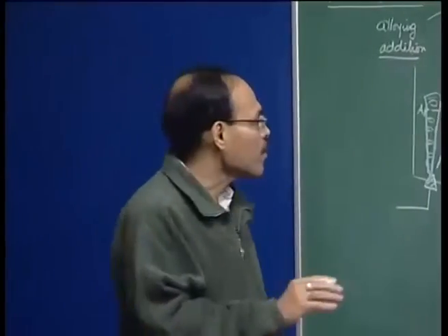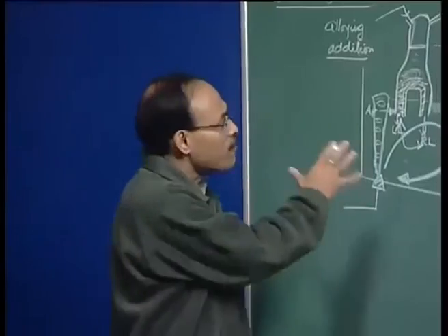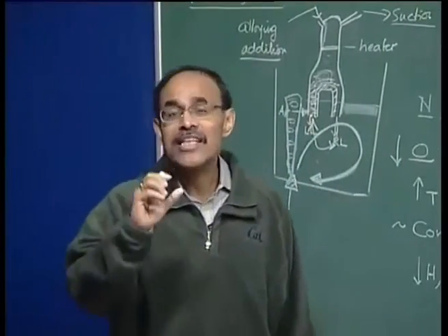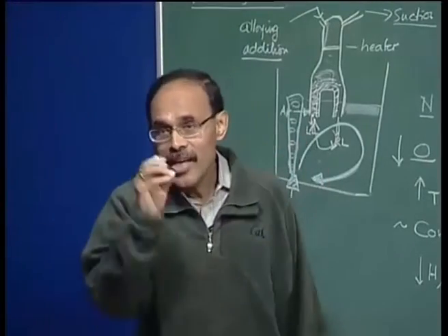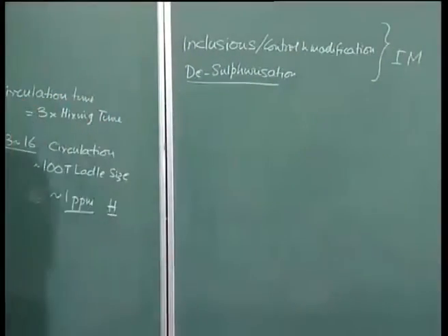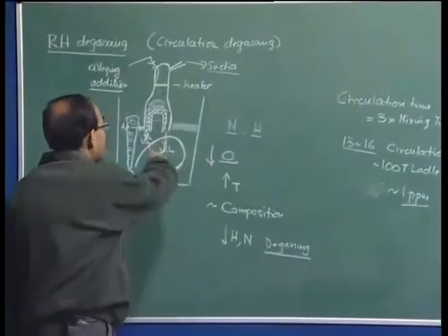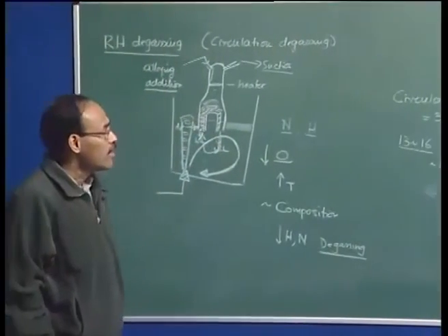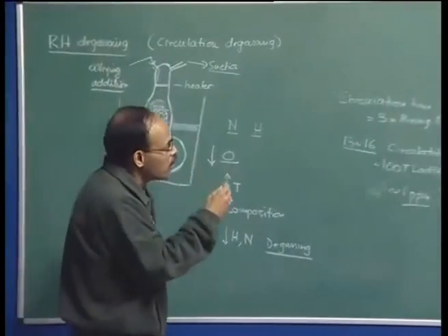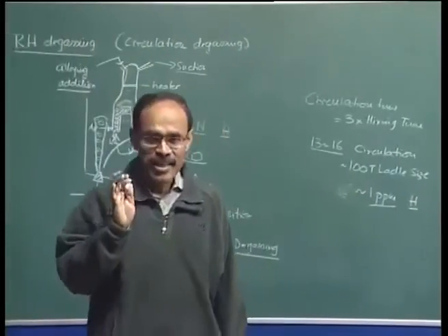So therefore, even beyond primary steel making, even beyond LF and vacuum degassing processes, we may have the sulfur content of the steel, depending on what kind of raw material we use, relatively high, and there we may be required to produce an ultra low sulfur steel. Also, we may have generated a lot of inclusions in the steel. We will talk about inclusions later on in this course, but let me first tell you that inclusions basically are unwanted and foreign materials in steel.